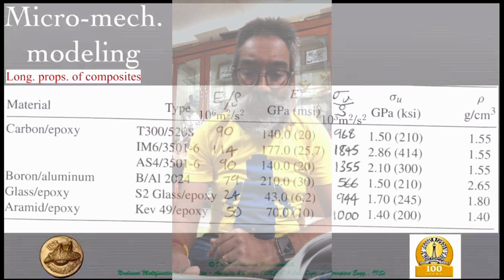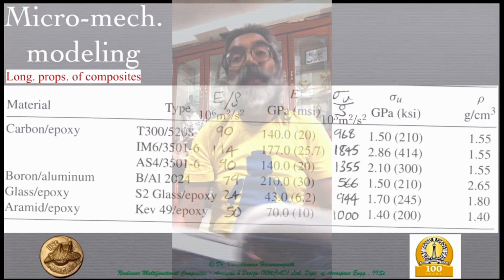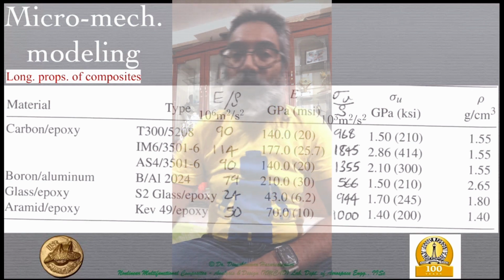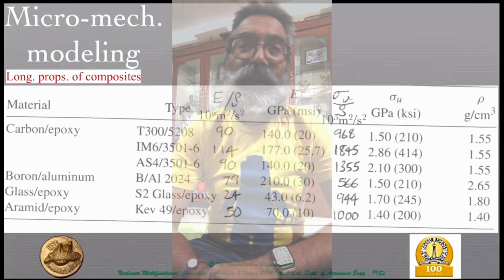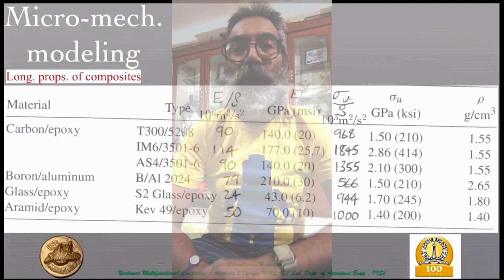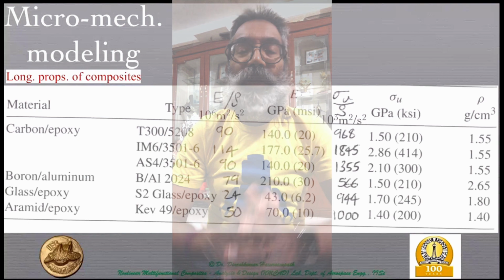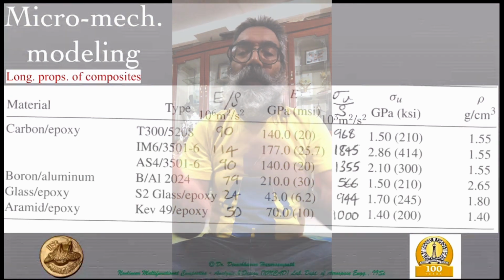So for the upper wing skin, which is subjected to compressive stress, fatigue is less of a problem over there. Because the fatigue properties of the 7075 are not as good as the 2024. So these are sometimes give and takes that you have to do in deciding upon a particular material.